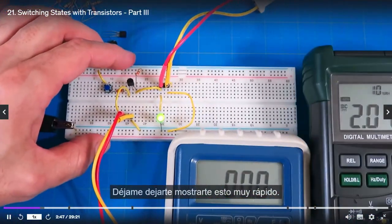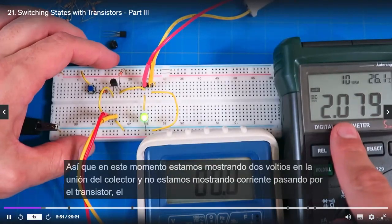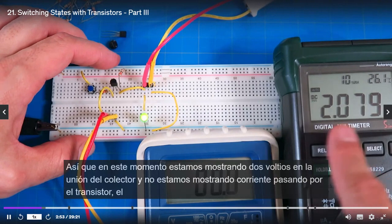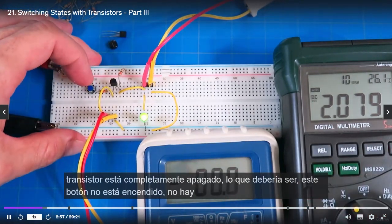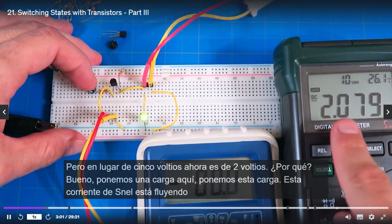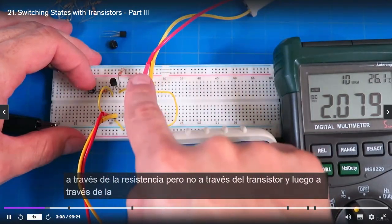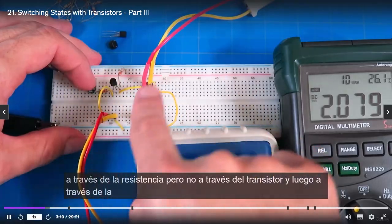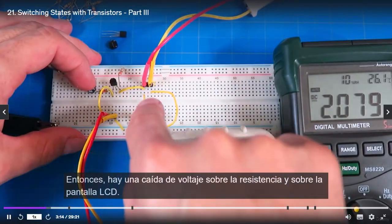Let me show you this real quick. Right now we're showing 2 volts at the collector junction, and no current going through the transistor. The transistor is completely off, which it should be. This button is not on. There's no base current. But instead of 5 volts, now there's 2 volts. Why? Well, we put a load on here, this LED, so now current is flowing through the resistor, but not through the transistor, and then through the LED, so there's a voltage dropping over the resistor and over the LED.